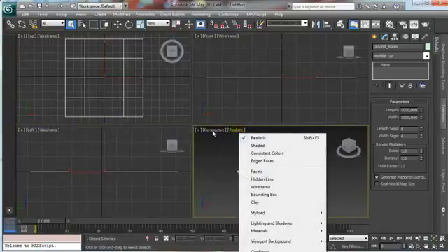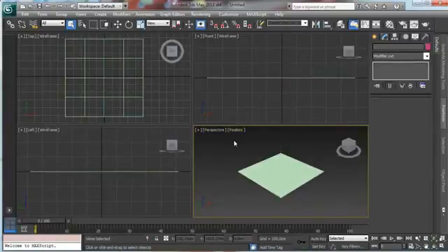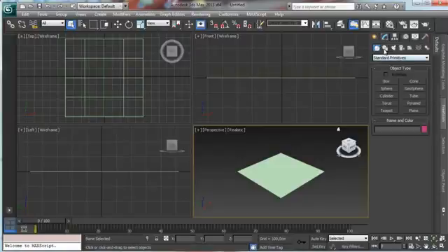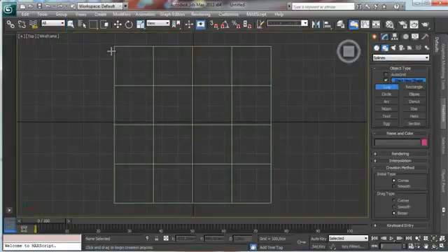Let's remove the grid using the G key. Nice. So let's start creating the walls inside this room, and we'll have a bigger room and a smaller room on the other side. Let's use a line to create the outline of our room, and let's use a snap.